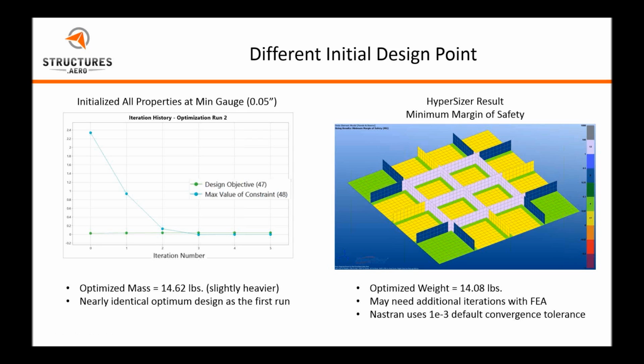You can define all sorts of failure analysis to use when optimizing, but it uses all closed form solutions and some iterative numerical solutions that aren't finite element analysis, but are based on experimental data and things of that nature. So it's very capable and fast, and it'll search through your entire design space, and it looks at all the possible design candidates and tells you the best one.